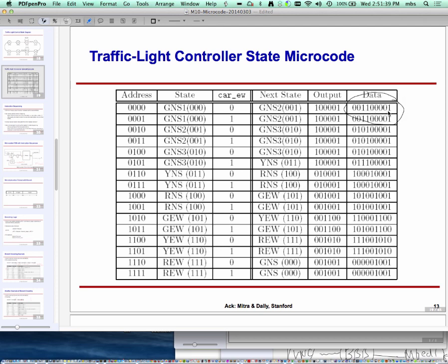So I'm asking, this data should be treated as a state, and the memory size should have as many data as many. No, this data is not the state. The state is the number of distinct addresses I have. This data is, remember, this memory is implementing my combinational logic, right? Originally in my sequential thing, I said all sequential logic can be implemented as a table lookup.